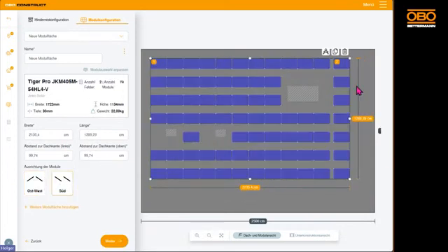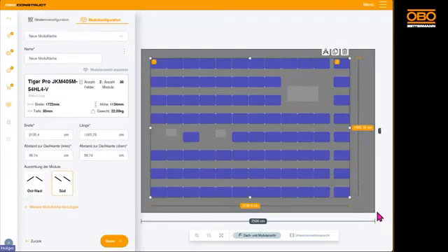Currently, it is always initiated in the east-west orientation by default. However, I can quickly switch it to a south orientation, and by using the mouse over function, I can now clearly recognize that these orange circled rows or areas create distinct separations between the individual module fields displayed on the screen. Because here, a thermal separation is necessary, since the total length of this rail needs to be separated after approximately 20 meters, where a second segment then forms.